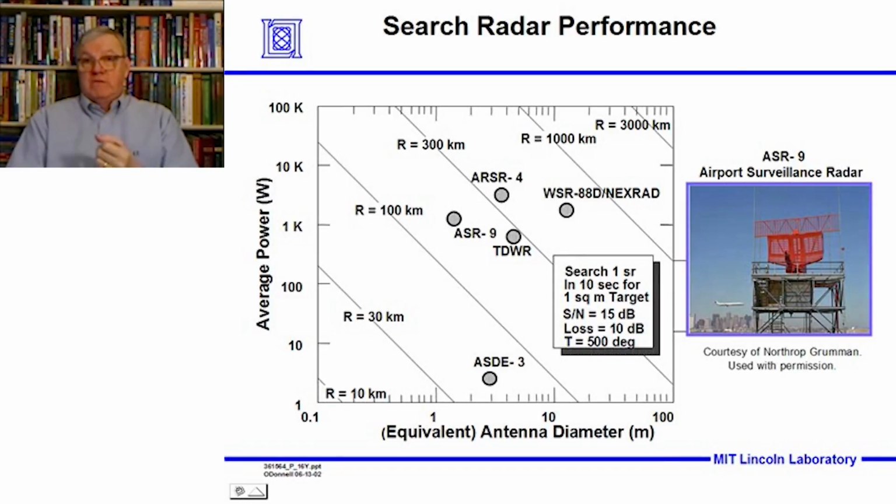Then, after receiving that signal, the beacon system will send back a signal, and on it will be coded a message with the altitude's height, with the aircraft's height and identification number. And this is obviously an ideal system, but many times on small aircraft, sometimes their beacon transponders in private aircraft don't work. The big commercial aircraft have redundancy for this.